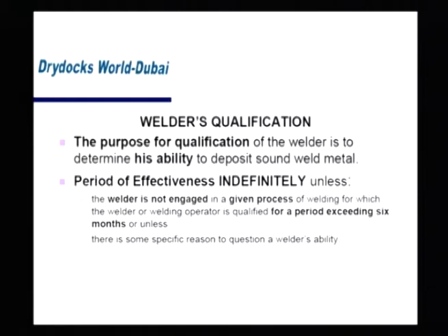Of course, you shall provide evidence that he has been working as a welder in the last 6 months. How can you do it? You can do it, of course, with an appropriate entity report. An appropriate entity report means that the entity report must give the process which is mentioned in the qualification. So you cannot submit, for example, an FCAW entity report if you want to revalidate the guy who is doing SMAW.